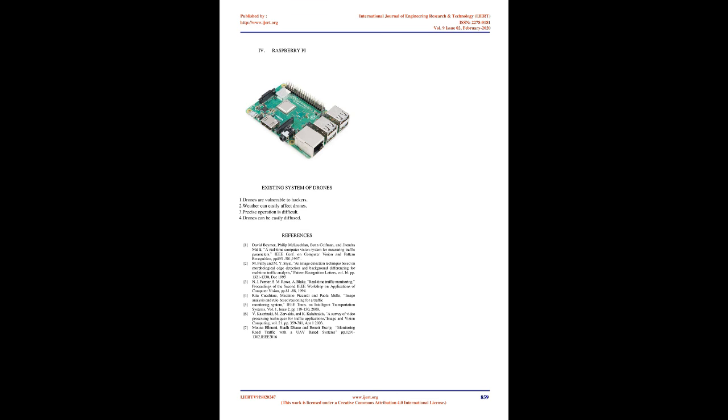Edge-based matching is the process in which two representatives, edges, of the same objects are paired together. Any edge or its representation on one image is compared and evaluated against all the edges on the other image. Edge detection of the reference and the real-time images has been done using the Prewitt operator. Then these edge-detected images are matched and accordingly the traffic light durations can be set.